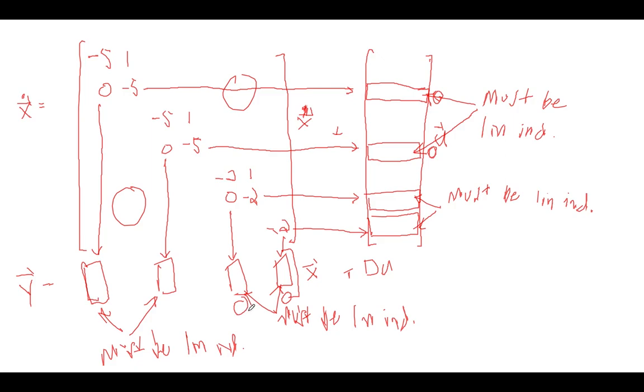So now we have the final tool we're going to learn for controllability and observability that, in my opinion, is the single best tool for controllability and observability, because we're already capitalizing on the Jordan form so much. It's such an important way to look at our system because it so clearly represents the states that are coupled and not coupled with each other and the underlying dynamic response of our system, because we can see the eigenvalues explicitly.